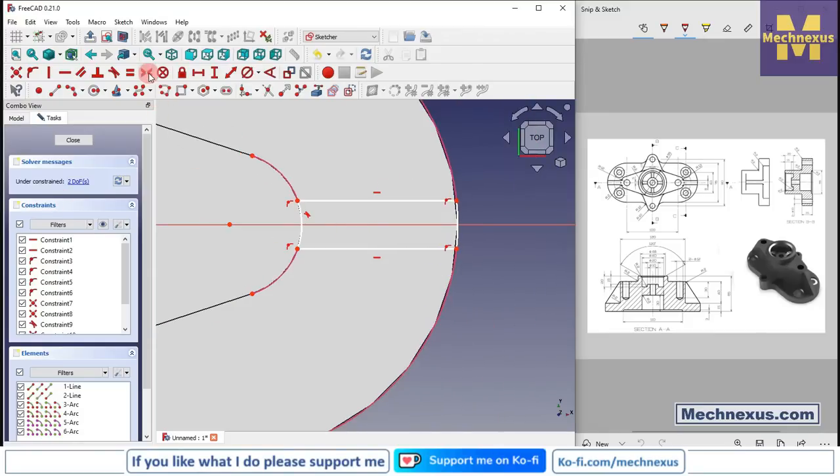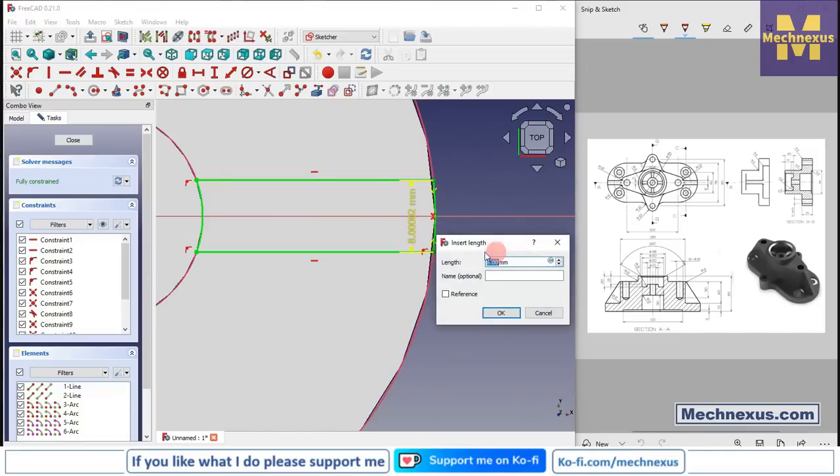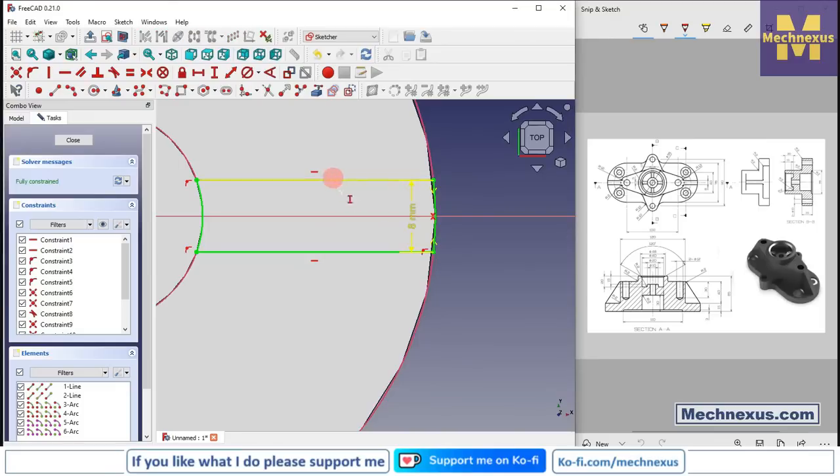Now we will use the symmetry, select this point and axis, and remove this conflict and select vertical dimension, select this point and provide the 8 mm. So here our profile is fully constrained.